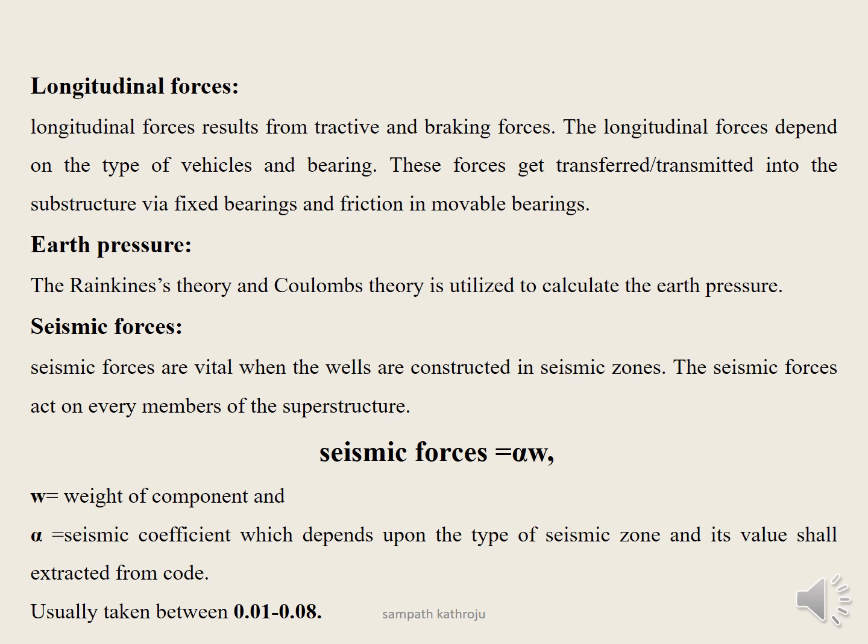Longitudinal forces are due to tractive and braking forces. Longitudinal forces depend on type of vehicles and bearings. These forces get transferred into the substructure via fixed bearings and friction in movable bearings. Earth pressure: Rankine's theory of earth pressure is utilized to calculate earth pressure on the portion of the pier, the portion of the well which is below the soil.